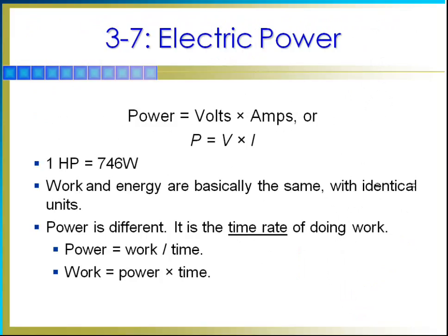So now we have Ohm's law. You see that from knowing two items, the resistance and the current, or resistance and the voltage, or the current and the voltage, from any two items, we can always calculate the third. We've got three different equations we can use based on Ohm's law to do it.